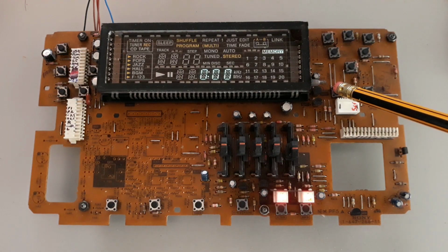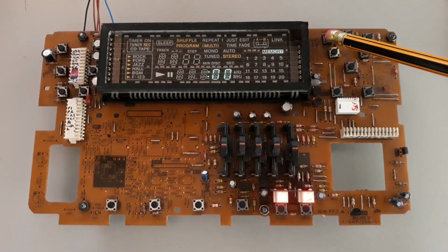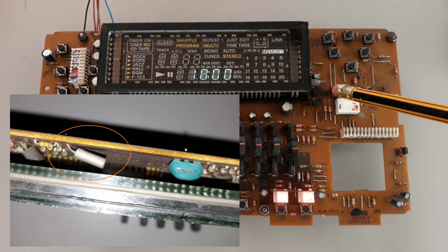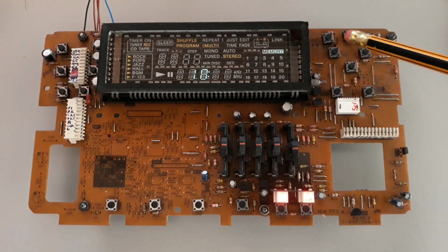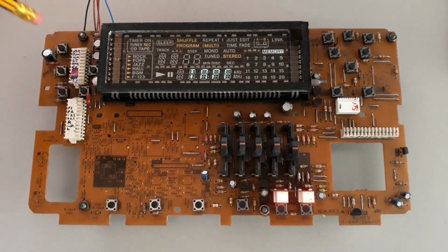As I often mention, one of the easiest ways to identify the presence of a real-time clock on a panel is to look for a 32.768 kHz crystal. Its presence is usually a very strong indication that the system includes clock functions. In this case, bringing the panel back to life is particularly interesting because of those built-in clock features.